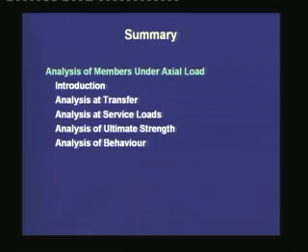First, we studied the analysis at transfer, where we found that based on the allowable stresses at transfer, we can determine the maximum amount of prestressing force that we can apply.